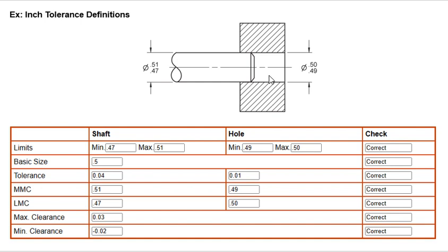Okay, for the hole it's a little bit difficult to understand, because you think like this part, the part of the hole, is the material of the hole. No, for the maximum material condition, meaning the most material has got to be on the part, okay, not how wide the diameter of that hole is, right? So pay attention to that. So that's why we put 0.49.